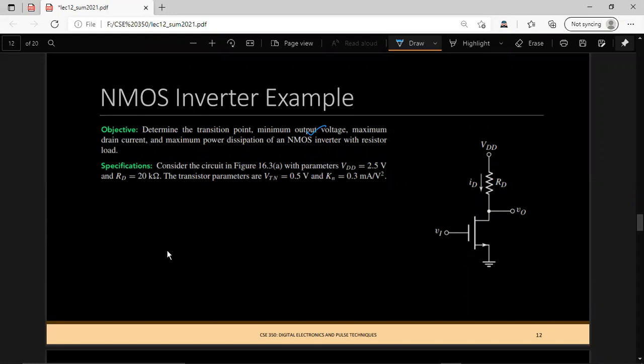And the maximum allowable voltage for this configuration should be about VDD, because in usual circuit design we connect the maximum voltage to the VDD terminal, so it must be the maximum voltage we could apply to the gate terminal. So we would get the minimum output voltage when the input voltage is 2.5. That will give us the minimum output voltage.